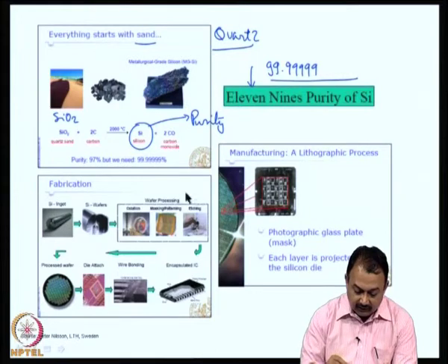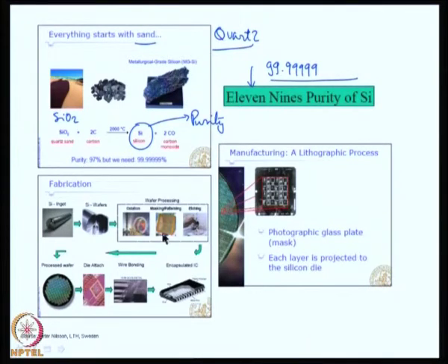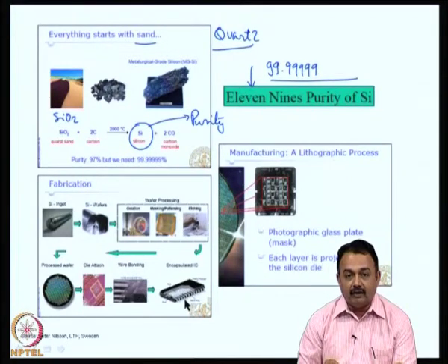Then the wafer processing takes place, including oxidation, imaging, patterning, etching, and then the processed wafer is now ready for die attach, which I explained. Then comes the wire bonding and then encapsulating the IC in a plastic package to define the final package format.